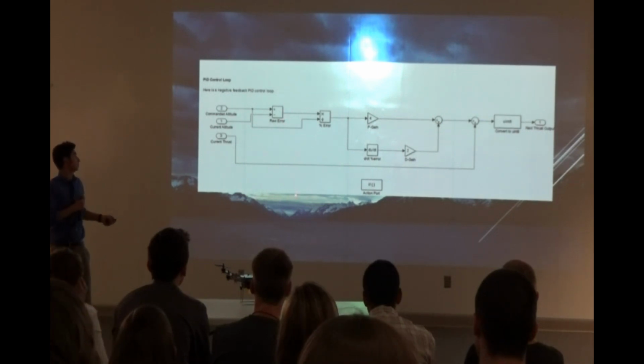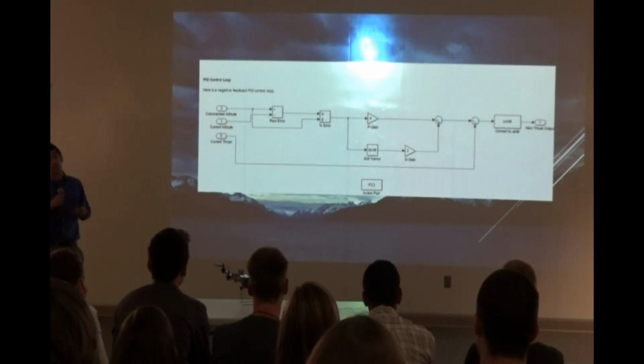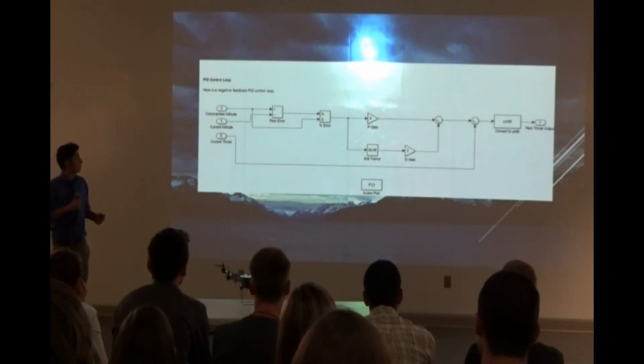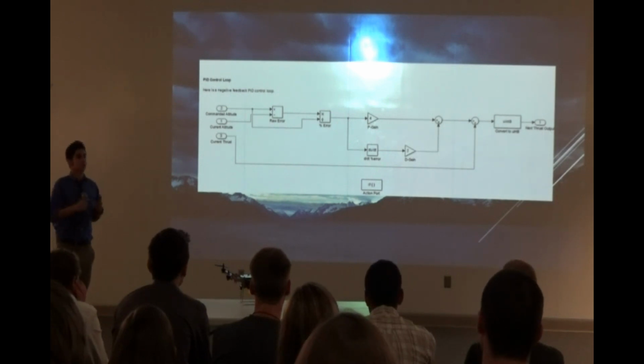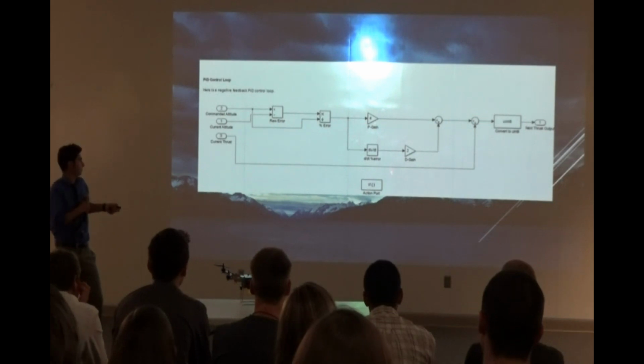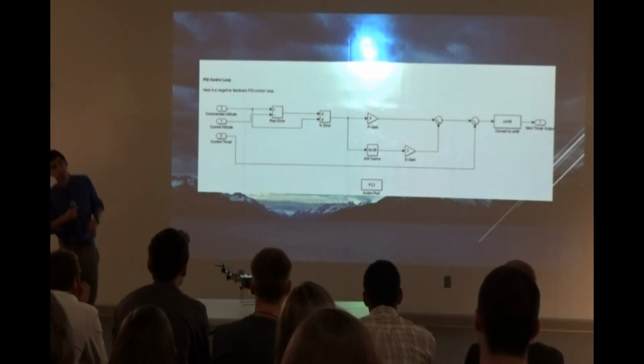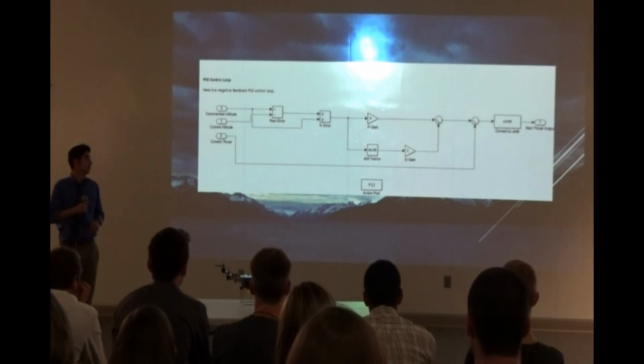And so we calculate the raw error between the two, and then the percent error, and then we multiply it by a gain value. And so all that means is we can adjust how much it reacts to error. And we also have a derivative of error, or the change in error as it goes over time.